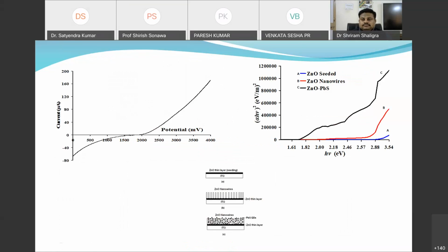In the same way I discussed with you, these are nanorods, for example zinc oxide nanowires. We can put them over the quantum dots. This is an ITO glass. So this kind of deposition methodology we can utilize for the solar cell. It is very interesting that if you don't have the nanowires, obviously your surface area will be smaller. These PbS quantum dots are nothing but your sensitizers. You can attach them onto the top or maybe inside the nanowires. So this is the methodology.